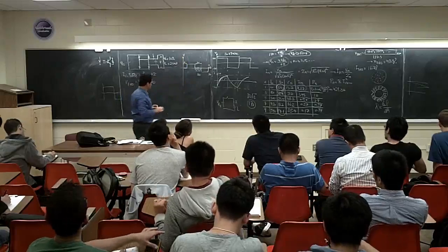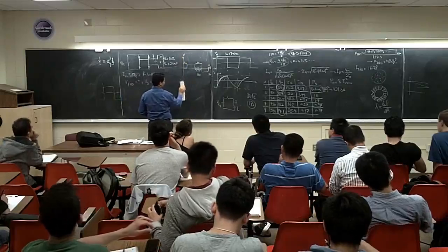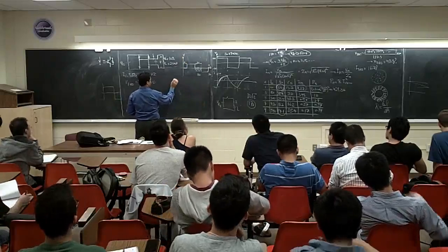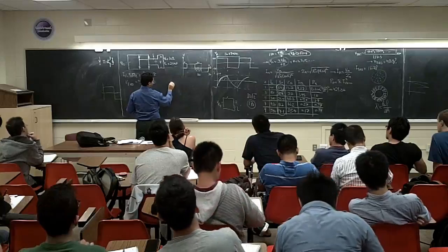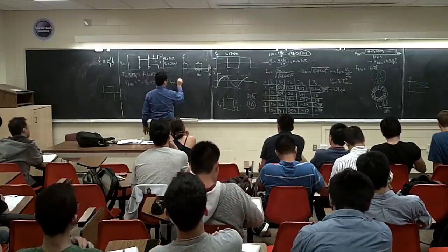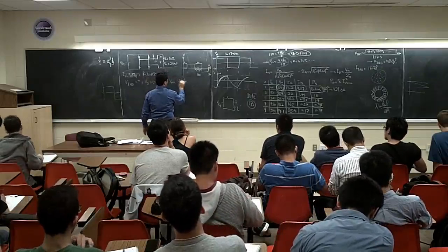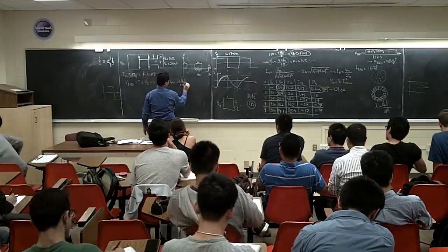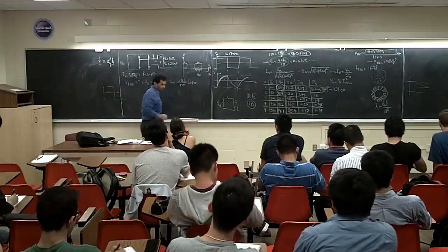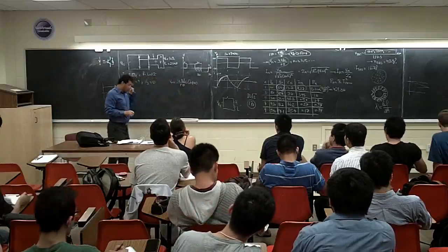Now, what was the equation for the voltage? I think we had this one. We said if we have this Vn, it's going to be 4 VDC over n pi, I think, cosine of n alpha, right? You should have it in your notes, right?